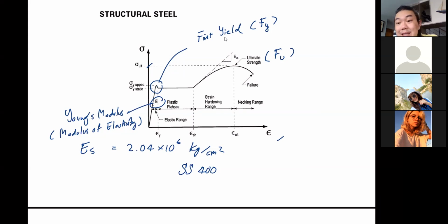SM400 seems to be more appropriate in all-purpose structural work, but SS400 is not going to hurt because it's essentially the same in terms of strength. And people used that until there's no longer SM400. So even though what we should use is SM400, you cannot indicate SM400 in your drawings or your design because you're not going to be able to find one. But don't worry, it's pretty much the same. Then another one, we have SM520. The number is bigger, so it's stronger. And right now, the price is pretty much the same. So SM520, of course, it's a better choice.